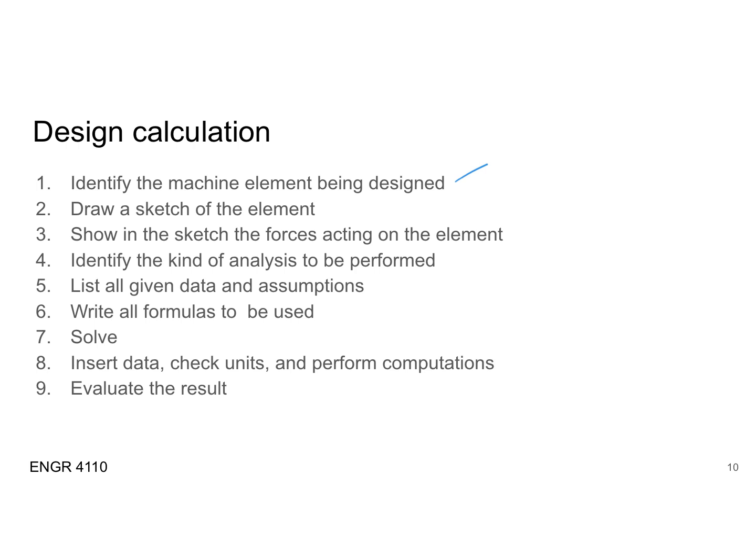So we can draw kind of the shaft there, and so we will have the reactions. Draw the sketch of forces acting. So this is force for bearing 1, there is force for bearing 2, and then there is force from the gears. Okay, and then there is an input moment here.